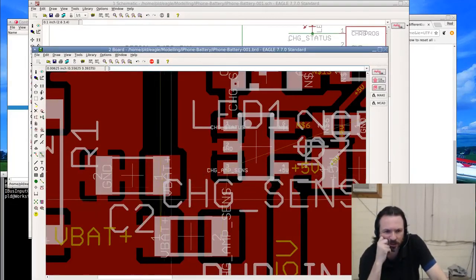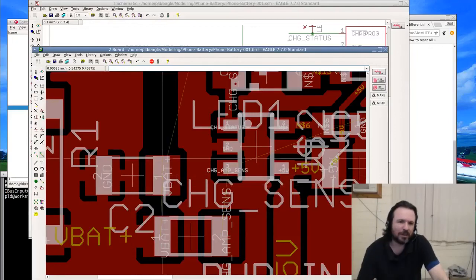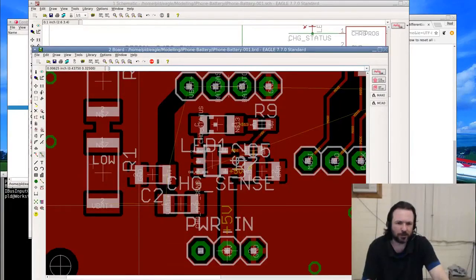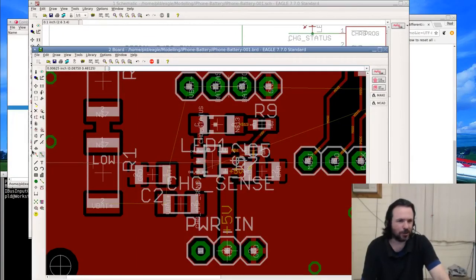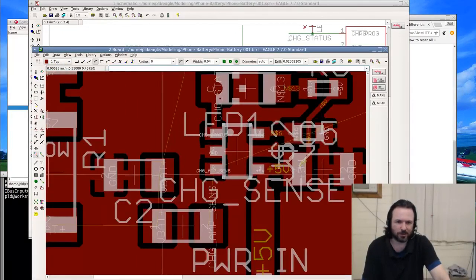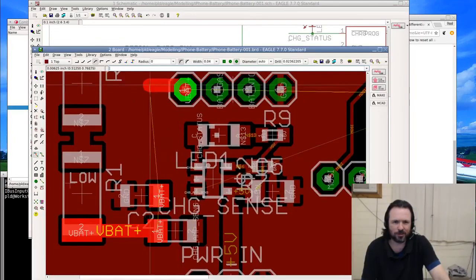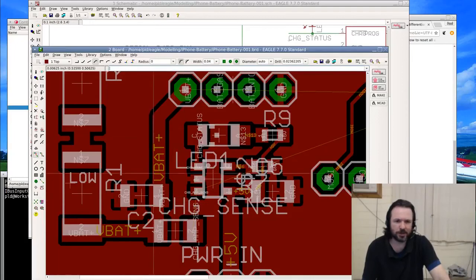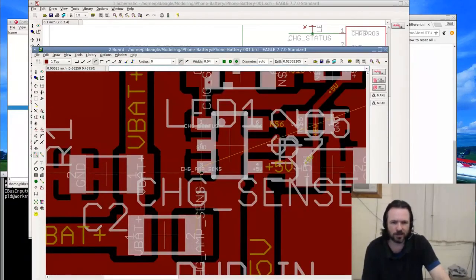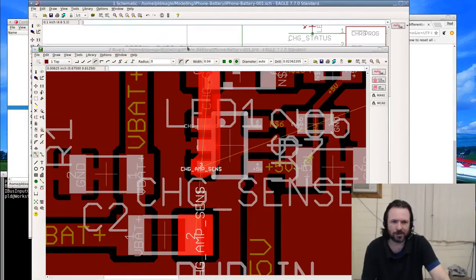This is one thing where Eagle really can be a pain in the butt, is if you haven't removed every little segment of your existing traces, then it can send you on a wild goose chase. It keeps saying there's a little piece in here or something. So if you do change your layout on something, you need to make sure you pull up every little last bit, especially the little segments hidden under the pads. Oh yeah, that's disgusting, man.